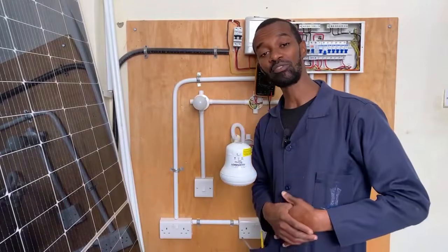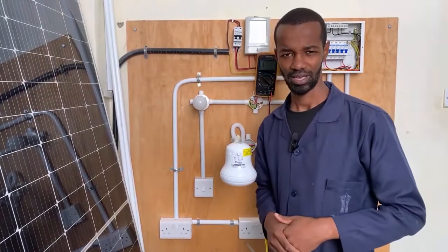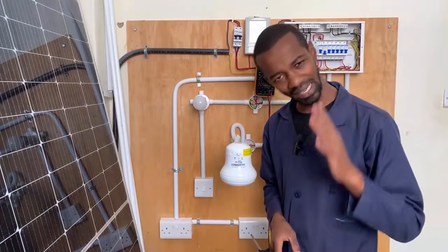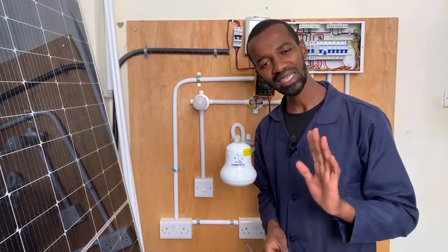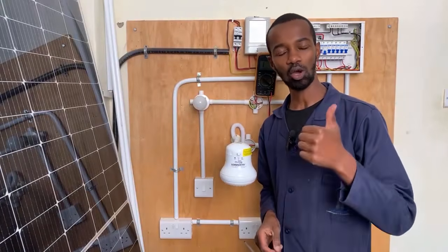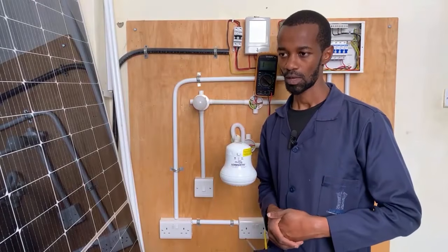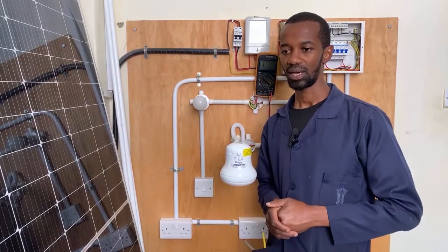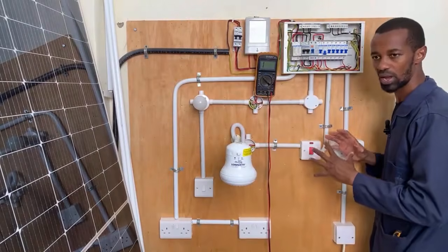If it is serving a kitchen where you have the microwave, isolate the microwave. Do not rush to power things on. You may power that MCB, probably the MCB was not faulty, and you are forcing it to turn on and it breaks completely. All right? So please ensure that you first of all narrow down where the problem is.